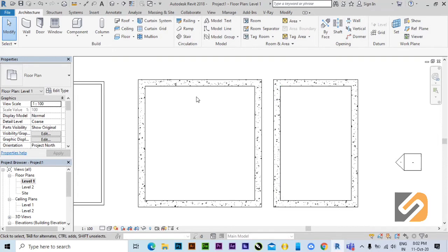You can think of these walls in the project as instances. You have a main family, and you are creating instances, which are copies of the original family, in the project. Once the original family changes, the copies will change also.